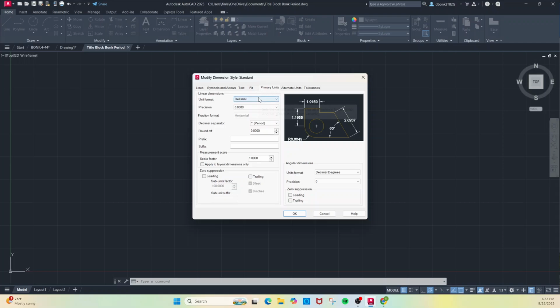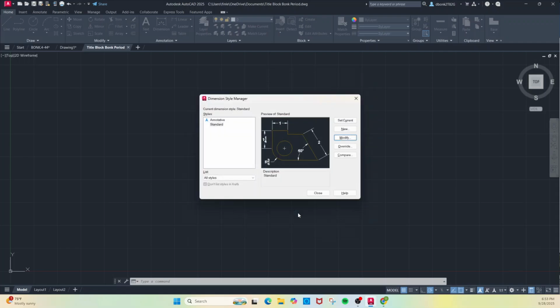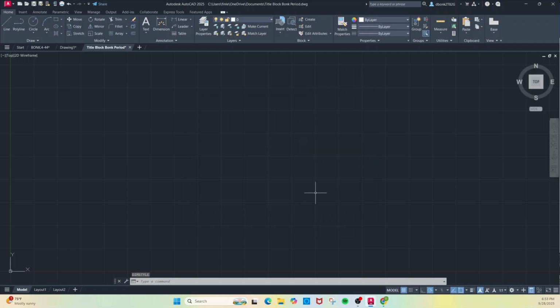This is what we've got to look at. Two changes here. Changing the decimal values to fractional, so you can see it in fractions there, and changing the precision to the third one down in the list. So everything is seen as you would see normal dimensions like we have on our measurements.